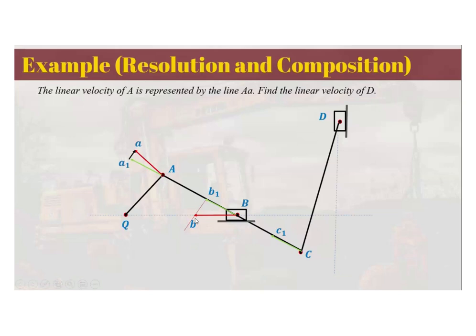So we now have two known velocities with their directions. For C, we are going to resolve it again using the velocities that we already know. So you are going to draw a perpendicular line, connecting the heads of the velocities of A and the absolute velocities of B. Since they are in the same line, their heads must intersect this particular line.